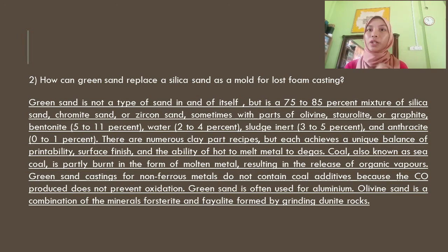Bentonite is 5 to 11%, water 2 to 4%, carbonaceous additive is 3 to 5% and additives are 0 to 1%.